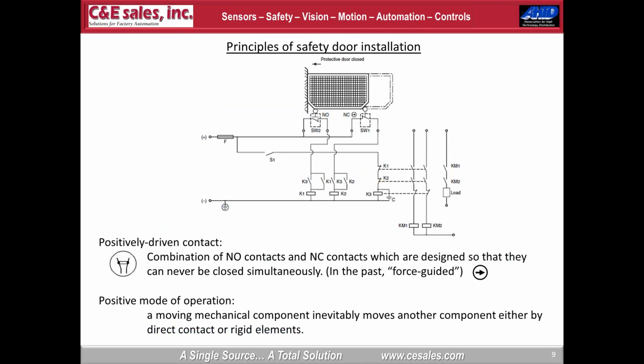Safety doors, I've spoken of this a couple times before in some of the seminars, but safety doors are a little bit different than e-stops. First, if we look at the bottom of the page, the term probably everybody is familiar with is force guided. Actually, the correct term to be used now is positively driven contacts.